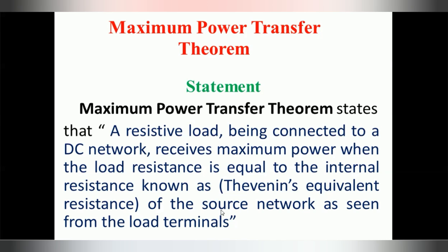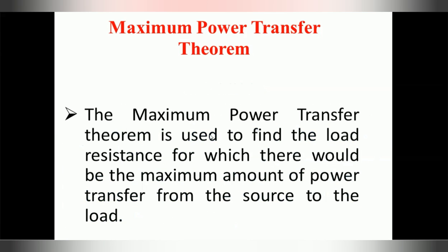Before solving problems related to this maximum power transfer theorem, we should be well versed in Thevenin's theorem, that is, Thevenin's equivalent circuit. While solving problems using this theorem, we need to simplify the network in terms of Thevenin's equivalent circuit. Then, with the help of the Thevenin's equivalent circuit, the load resistance value is replaced by the equivalent Thevenin's resistance value. The maximum power transfer theorem is used to find the load resistance for which there would be a maximum amount of power transferred from the source to the load.